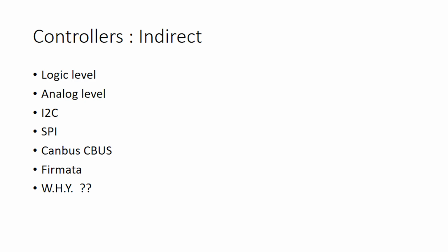But there's also indirect control. And that is that Arduino, or that RP2040, or that Pico, it's got one wire driving all the NeoPixels. So it's got all these other pins. So you could, for example, drive one of those other pins from a TOTI. And when the TOTI comes active, because a loco has entered the section, then that starts the NeoPixels that are driving your level crossing lights, as a for instance. So these are indirect controllers that will control your controller.